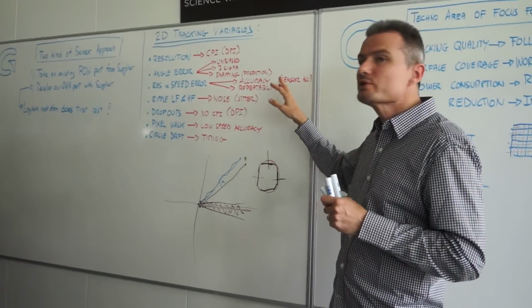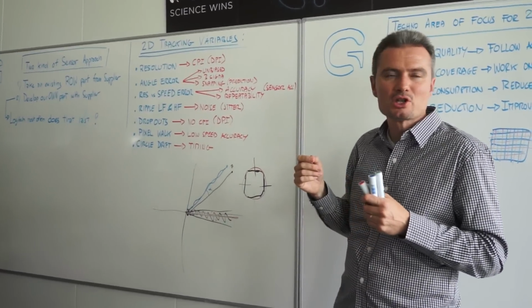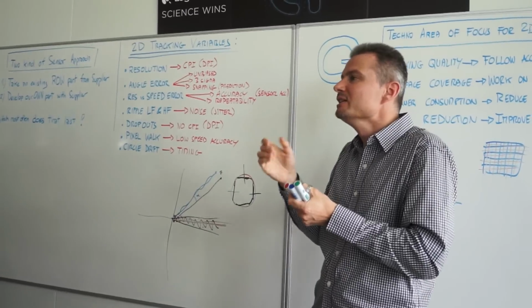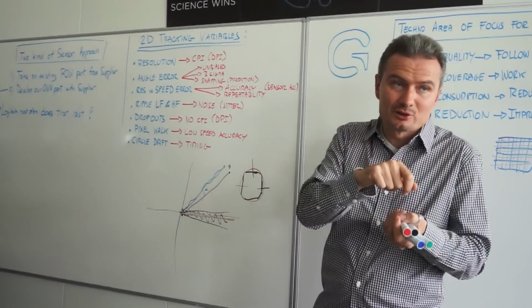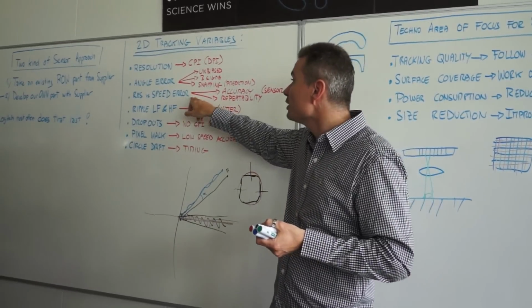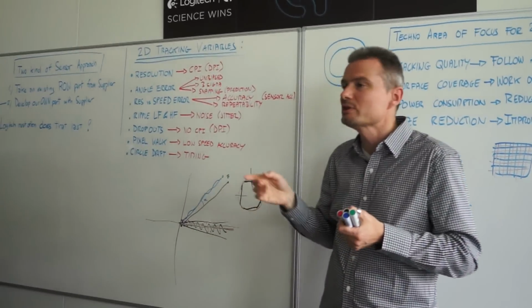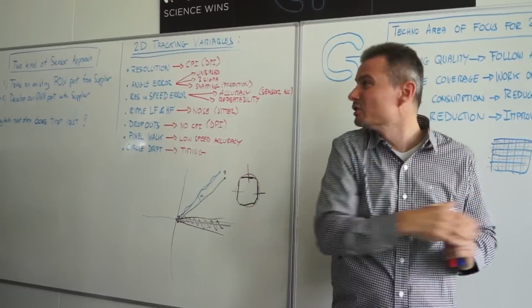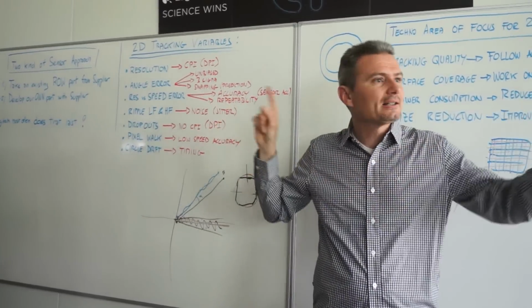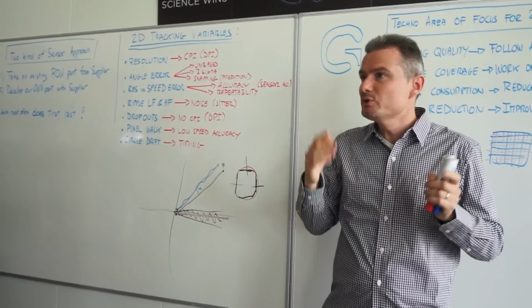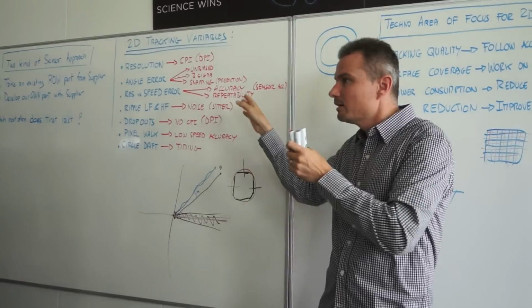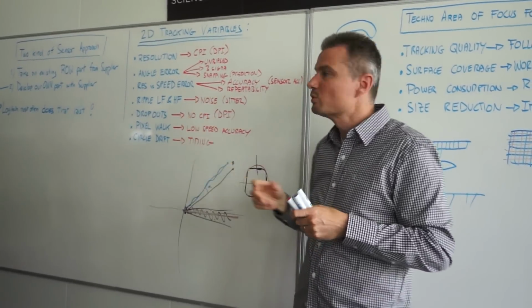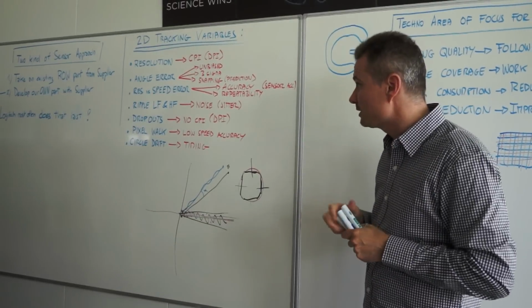And here, the users, by the way, call it sensor acceleration. It's not sensor acceleration. It's a sort of misinterpretation of the sensor with respect to the speed. So the sensor doesn't have the ability to see the same number of counts if you move it slowly than if you move it quick. And here we worked a lot to improve that point for gaming sensors, because we know that gamers, especially FPS gamers who want to do headshots, want a system that is precise. They know there is one that is coming here and another one that is coming there, and when they do this movement, they come exactly at the right position to shoot both guys. If you have a bad mouse, then you will overshoot. You will end somewhere apart, or before if you undershoot, but whatever it is, you will have a problem with this parameter, what we call resolution versus speed error. So this is an aspect we try to look at.